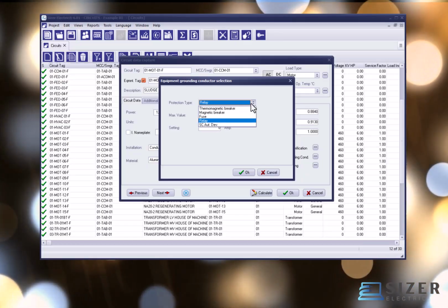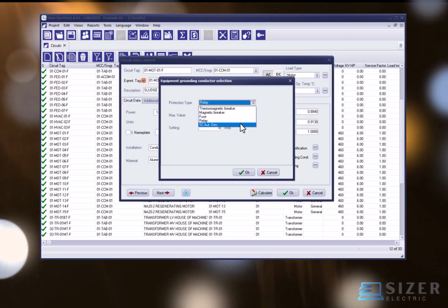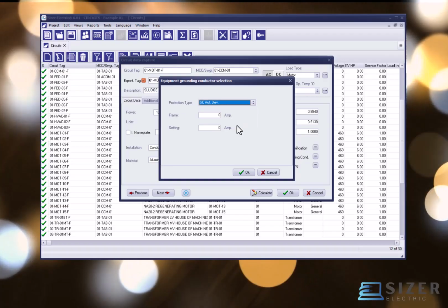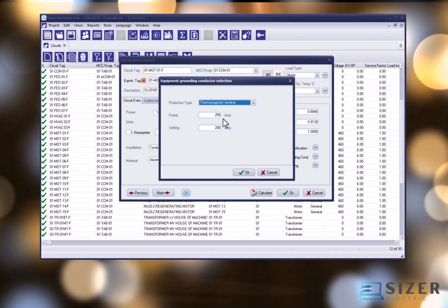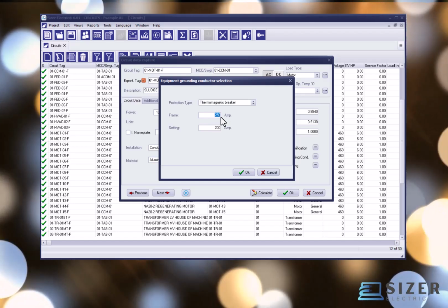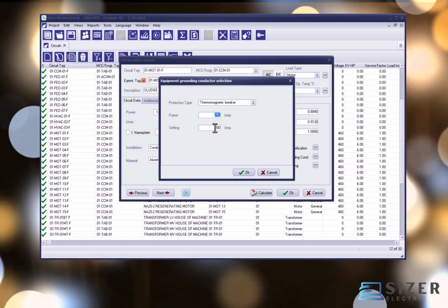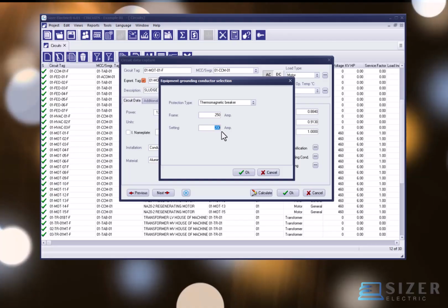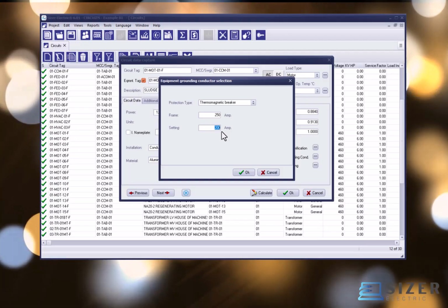If none of the options displayed in the protection type field describes the device used to protect the circuit, the option Automatic Overcurrent Device may be selected, which serves as a generic reference for any protection device. Although this window requests the second field, frame, fuse holder, or maximum setting, this value is used only to complement and populate the conductor schedule report. In practice, it is the third field, identified as setting or fuse, that is used to select the initial equipment grounding conductor size, in accordance with Table 250.122.